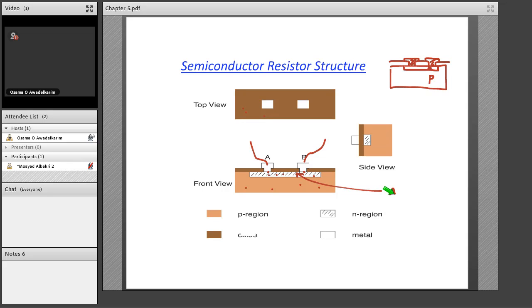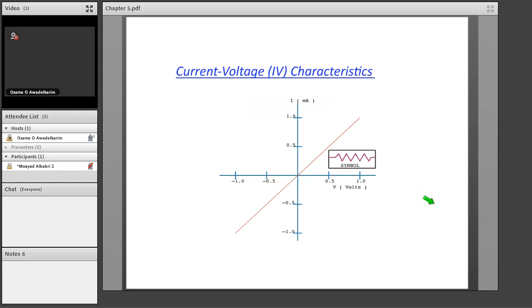N-type meaning that we engineered it in such a way that we dope it with phosphorus, and so N is equal to the number of dopants. We saw that for an N-type, the number of dopants determines the free concentration of electrons. And we know from our electrical engineering studies that the IV characteristic of a resistor is linear.